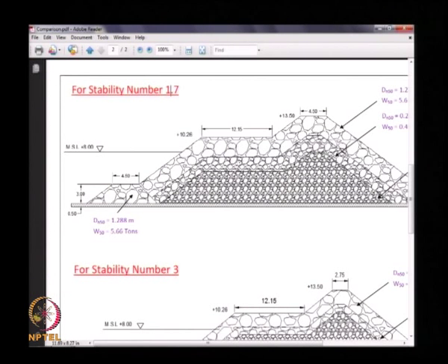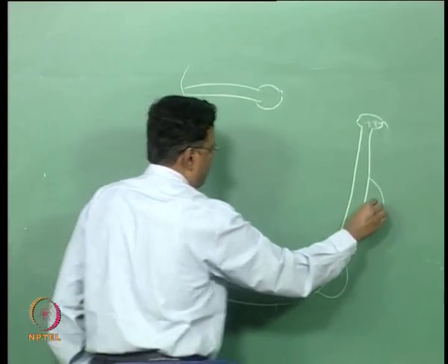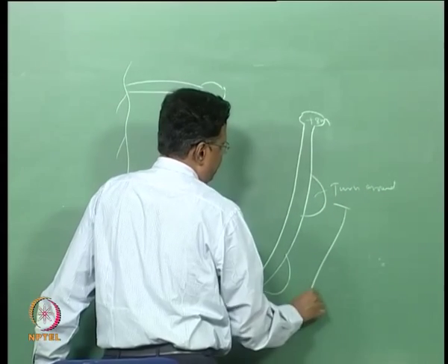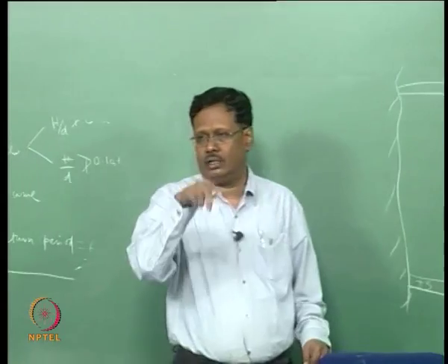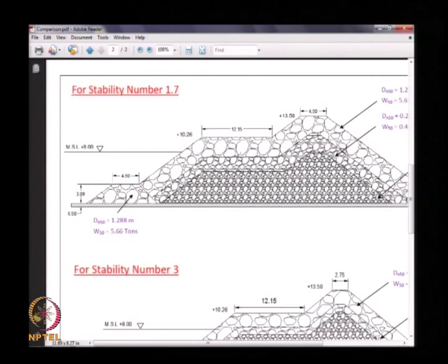One of the advantages of the berm breakwater is you have one road width to go forward, another road width to return, and this road width also is sufficient for going up and down. But if it is a conventional breakwater, they will be constructing some areas where the vehicle can turn around. Typically every 500 meters or 300 meters center to center they will have these turnarounds for the vehicle to turn and come back. These are all construction requirements which you have to consider.